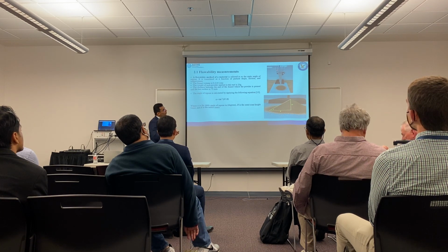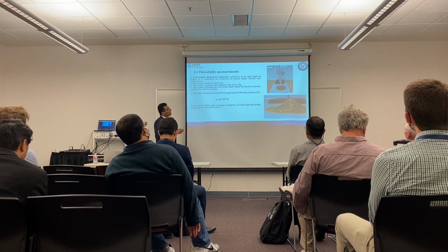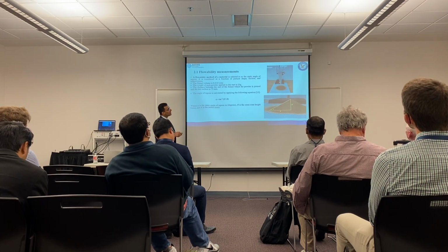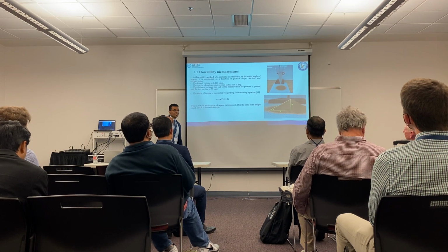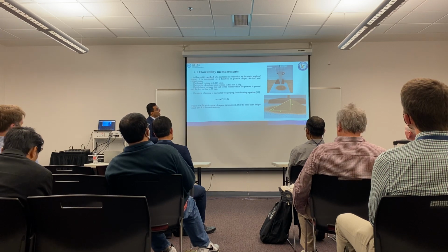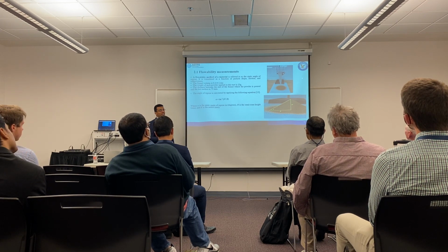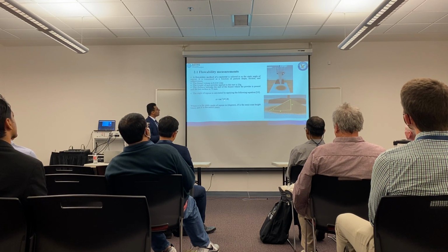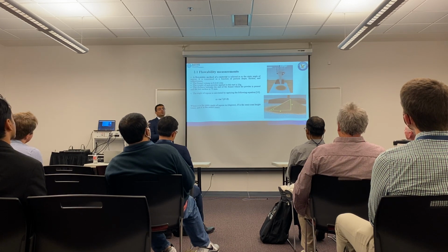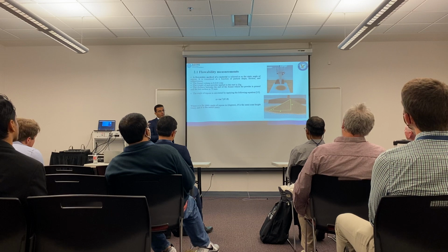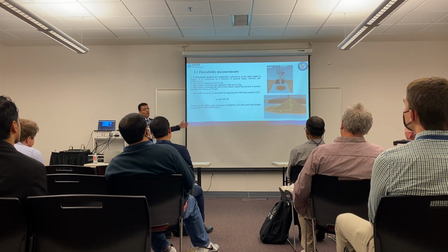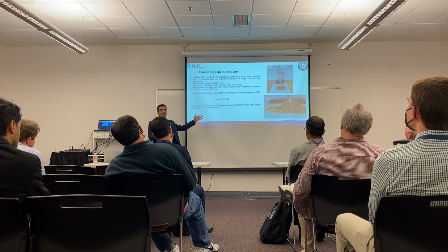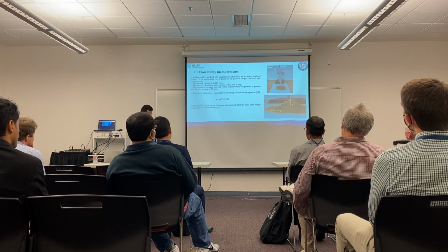We poured the powder into the upper stage of the funnel, and it smoothly and continuously distributed to form a conical heap of powder. Then we could measure the height and radius of this heap. After that, we applied alpha equals tan inverse of h divided by r to get the angle of repose for each one. We also ran this 5 times for each powder.